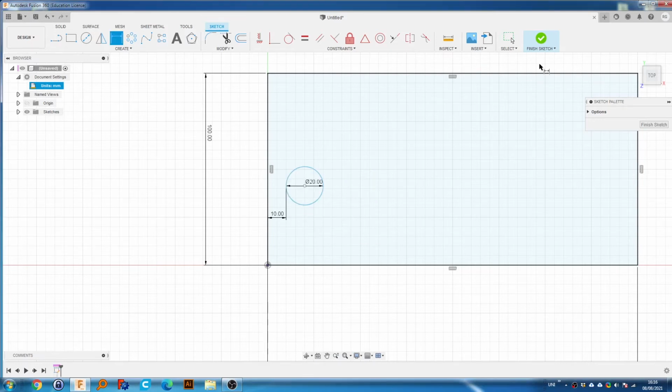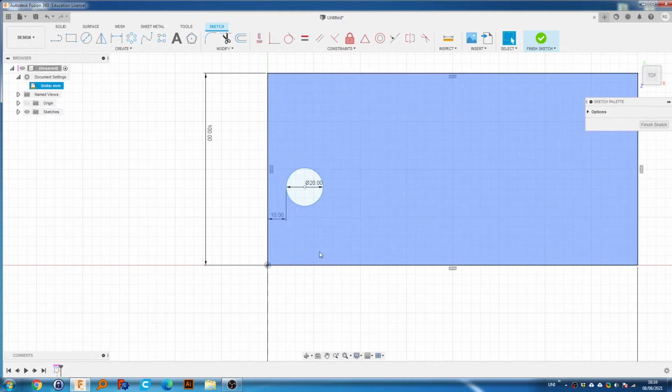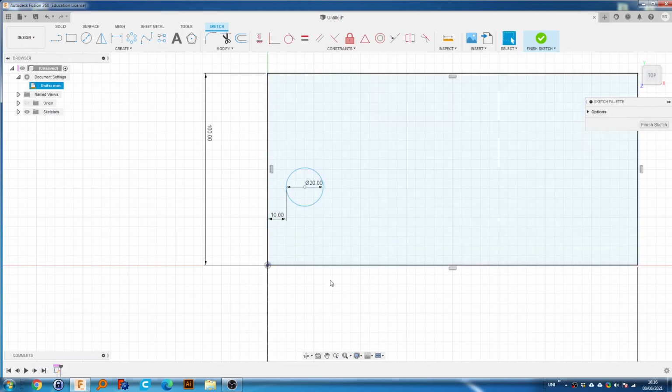But you can see it's still blue. So to get over that, we can move it about. Oh, which way is it going, which it shouldn't be able to go? It's going up and down. So we can fix that by doing what we did before. We can right click after selecting sketch dimension and click tangent and click here. And type in something like 10.